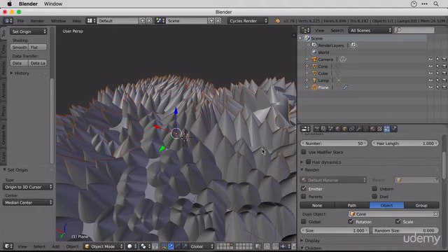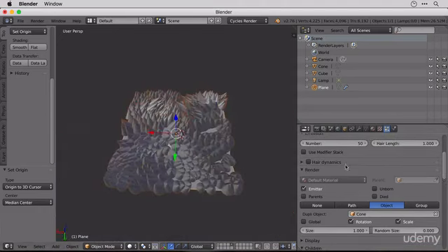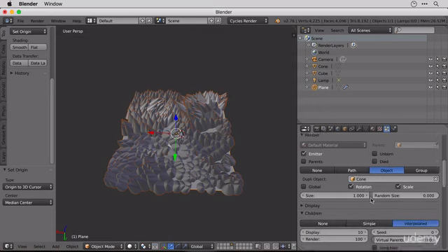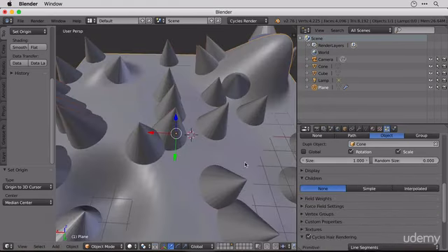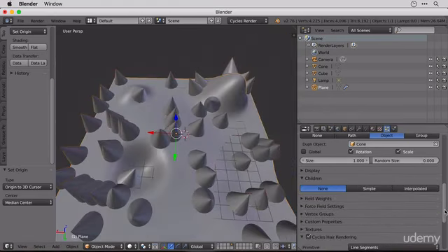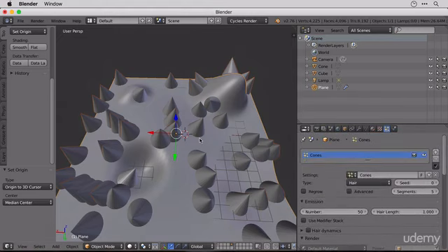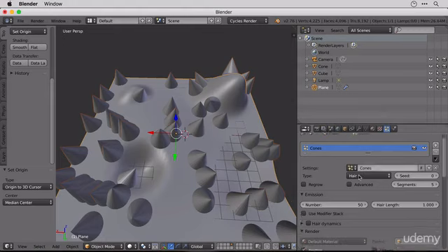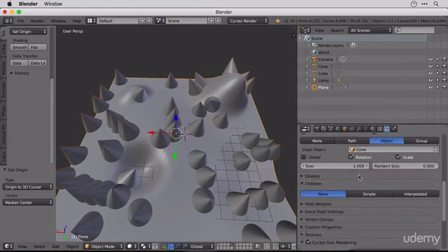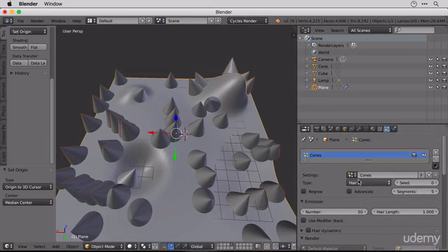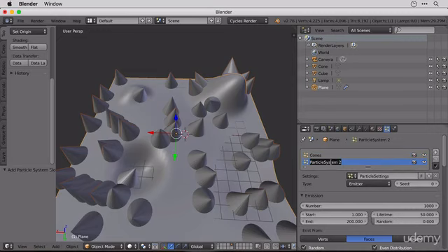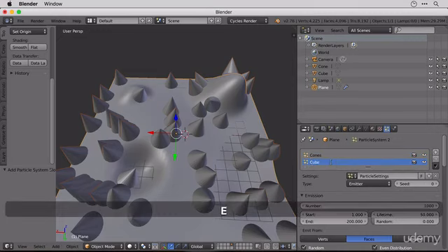geometry. Now, one final thing, let's turn off children for this moment in time so we can see what's going on. Let's go and add another particle system. So I would always recommend, if you're using one particle system and you've got loads more that are going to be similar, that you get one of them right to begin with, because we can borrow those settings with a new one. So let's set up a new particle system and call it cubes.